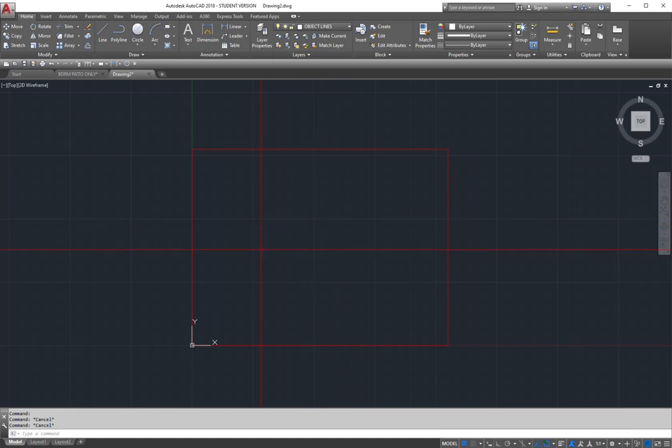And it tells me that I need to start at point 2.375, 5.875. Remember that the very first point that we start working with is always going to be an absolute value. It's always in reference to the 0, 0. And after that, we remember that we needed to activate this dynamic input command. So if we go to our status bar and make sure that the dynamic input is blue, that means it's active, then we don't have to do the absolute, relative, and polar ways of inputting our information as we did previously.